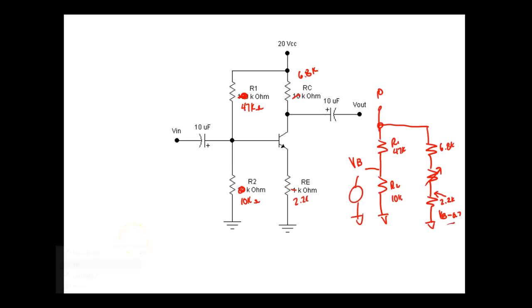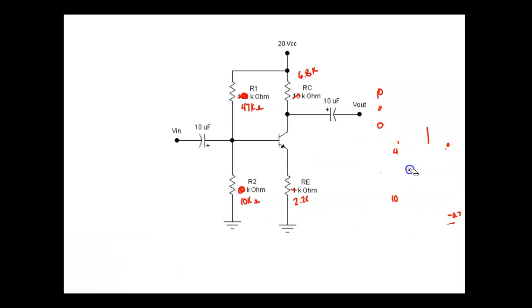So what I'll do is I'm going to erase this. Whichever way you want to do it, it's up to you. You can divide RT into 10 volts, and then take that and multiply it times R2, and that would give you the current, like you learned in DC. But what we find out is it's a lot easier to use what we call the voltage divider.